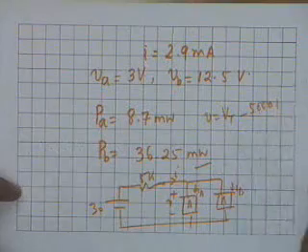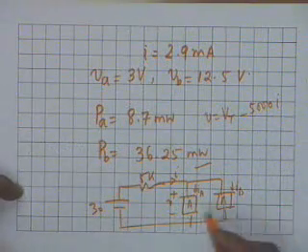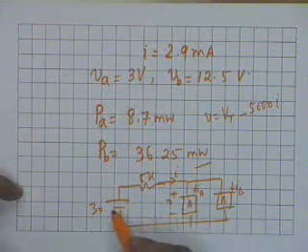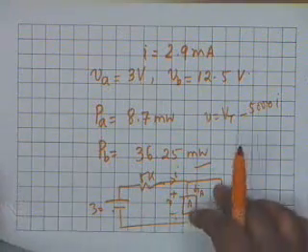Alright. But the load line for this will be the same. That is V equals Vt minus 5000 I, where I is in amperes. The load line will be the same, because this V is this voltage minus the drop in 5K. Alright, is that okay?